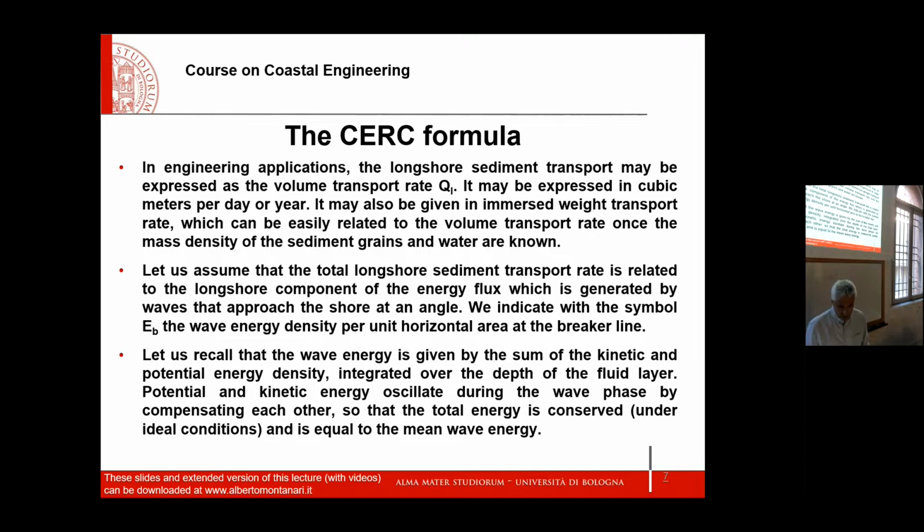And you see the assumption is the second bullet point. Let us assume that the total longshore or alongshore, they are synonyms, sediment transport rate is related to the longshore component of the energy flux, which is generated by waves that approach the shore at an angle. Let me explain better. And let me draw another coastline.